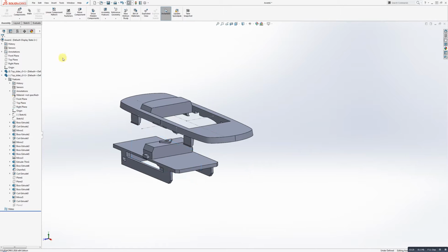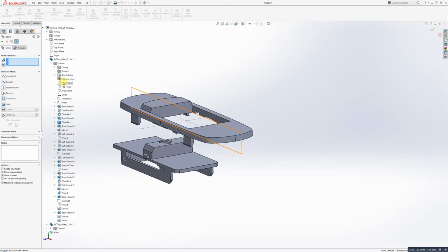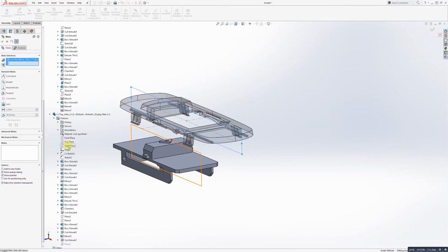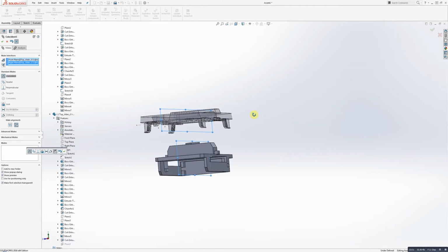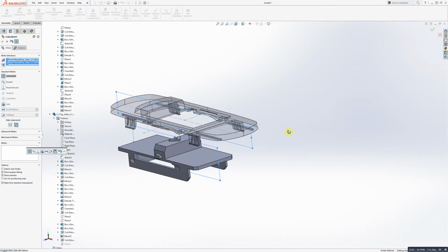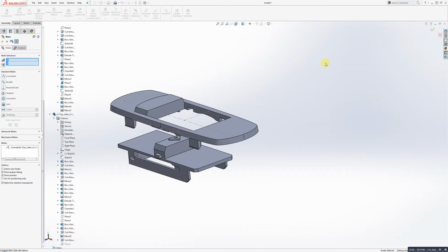Okay, so what I want to do is set a mate that lines up each of the planes that are in the center of the model. So between this plane and the right plane here, and watch them slide over. Boom, there you go. So now these two models are perfectly orientated together, centered on each other's axes. This is the final result, the final success of building a model off the origins. Why I've been saying it since the very start.